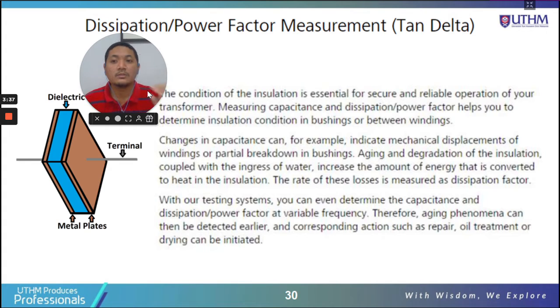Aging and degradation of the insulation, as well as ingress of water inside the insulation material, can cause changes to the total value of the capacitance.